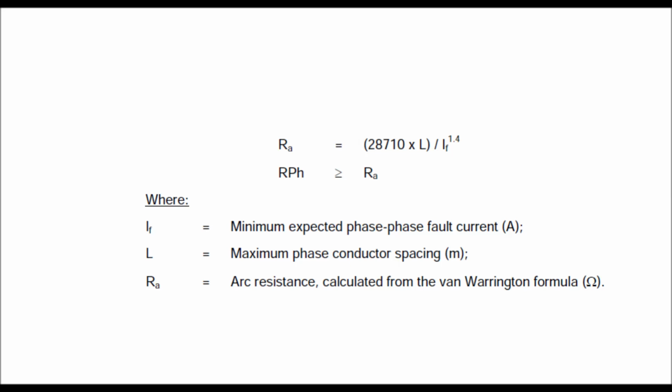Now for resistance reach calculation, for a phase-to-phase fault, the resistance reach must cover the arc resistance value.